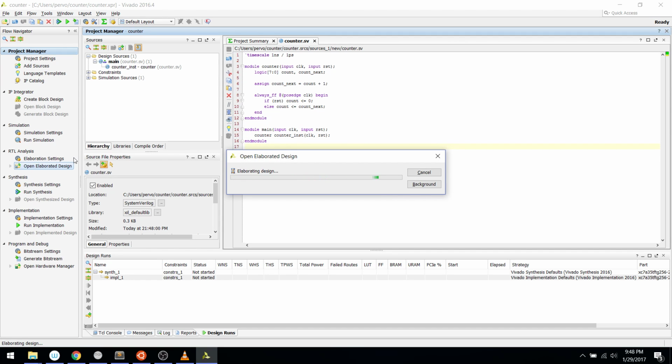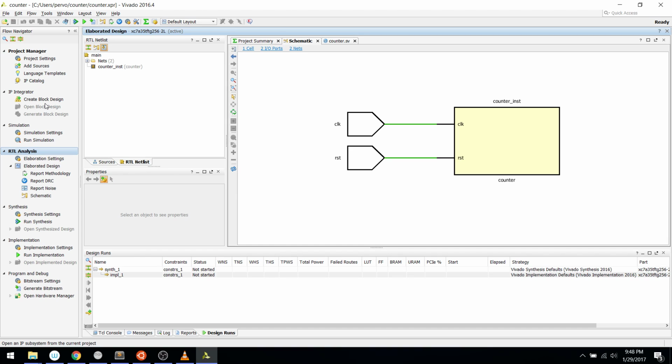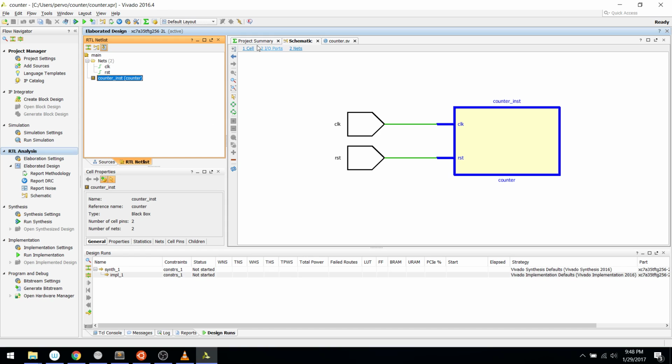is go to the whole process of RTL development, which is this multi-stage process of going through different compilation stages. What is called elaboration is the first level of compilation. So what you basically see here is a schematic of what it compiled. The job of the front-end compiler that's part of this elaboration is to take your high-level source code and generate netlists, which are sets of cells that represent abstract blocks, and then the nets that connect them. So this is an abstract schematic circuit.